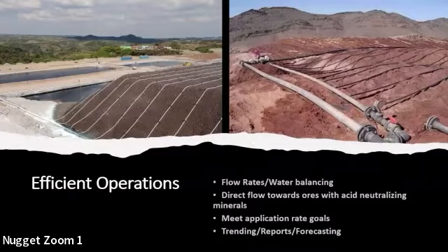An expectation after this analysis was to obtain all geotechnical parameters to perform further stability analysis. First, we did a general evaluation of whether any concerns related to dynamic or static liquefaction could be foreseen, read straight from the analysis of the CPTUs and the gathered data.